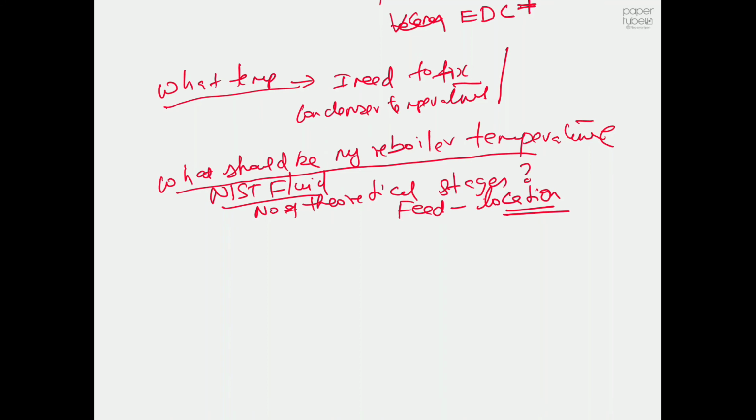And then we will do the same for the oxychlorination process. We will supply slightly excess HCl, and then we will mix those two product streams, the one which comes out from the oxychlorination and the product which we get from the direct chlorination reaction.